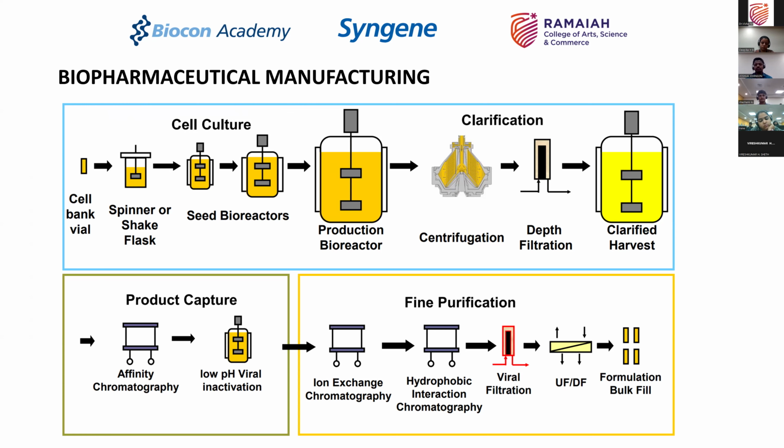Just to give you an example of, again, insulin manufacturing, if a production bioreactor was 60,000 liters, you would generally see a seed bioreactor N minus 1 at about 5,000 liters or slightly more. And then you would see the pre-seed bioreactor, which is about, say, 500 liters. So it's a scale of 1 to 10 generally that we have seen.